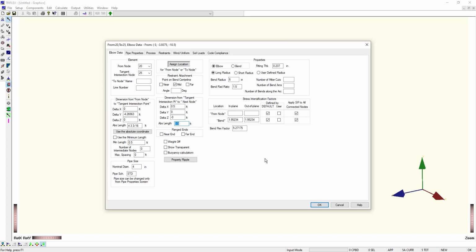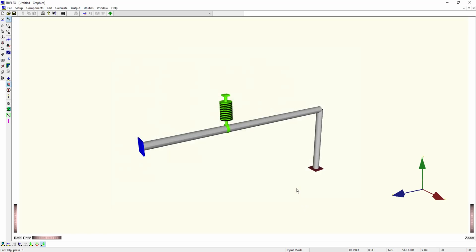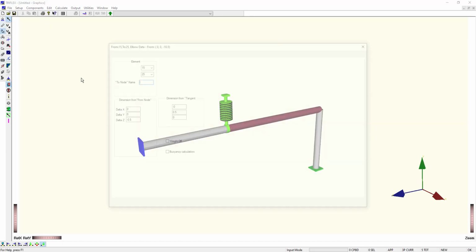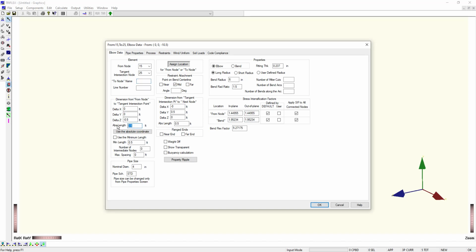I'm sorry, we're coming from the wrong place. Let me cancel that. You have to make this current. And that's a good way to figure that out too, because you want to keep going in this direction. So you want to make this component current. The red means current. All right, so pick up an elbow, and again go to our absolute length, 4 feet 3 inches and 3/16.